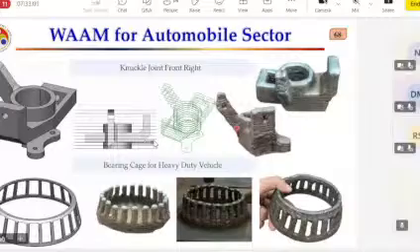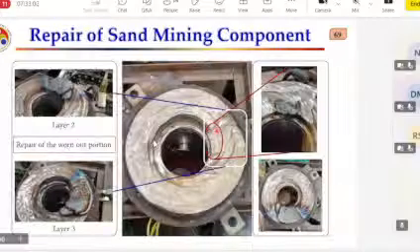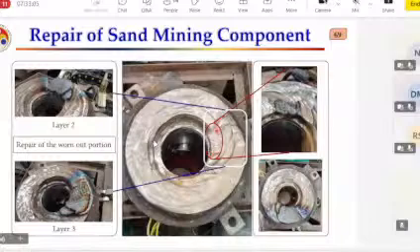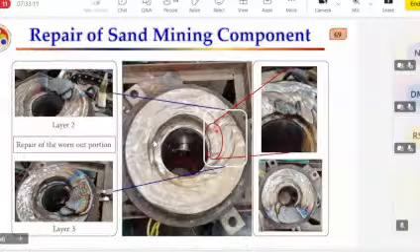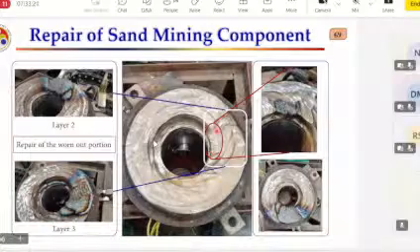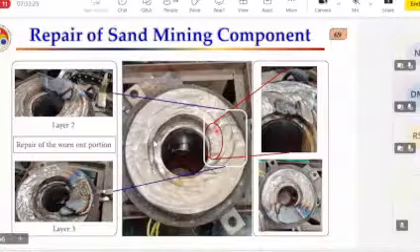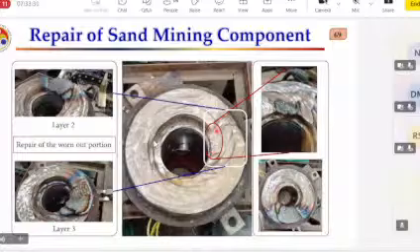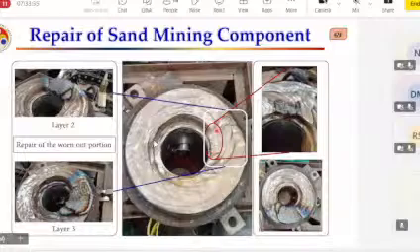Then another application that we can use it for is density-based FGM, like we can make some monomaterial density FGM by a hybrid process. You can deposit the layer, then you can use the drilling machine. Since you're using a hybrid setup, mounted on a CNC machine, you can quite easily machine it and vary the density by drilling holes inside it. And not only that, we can create these holes in such a way that we can obtain a particular density gradient.